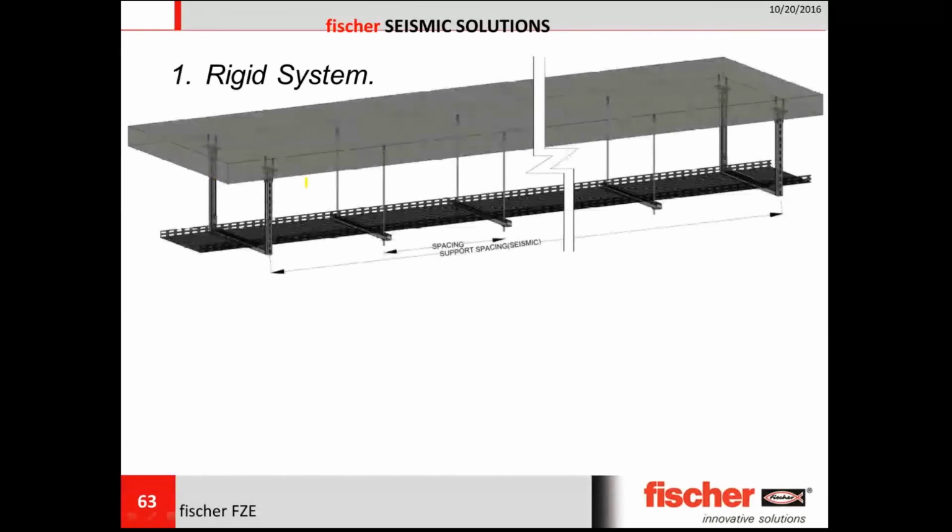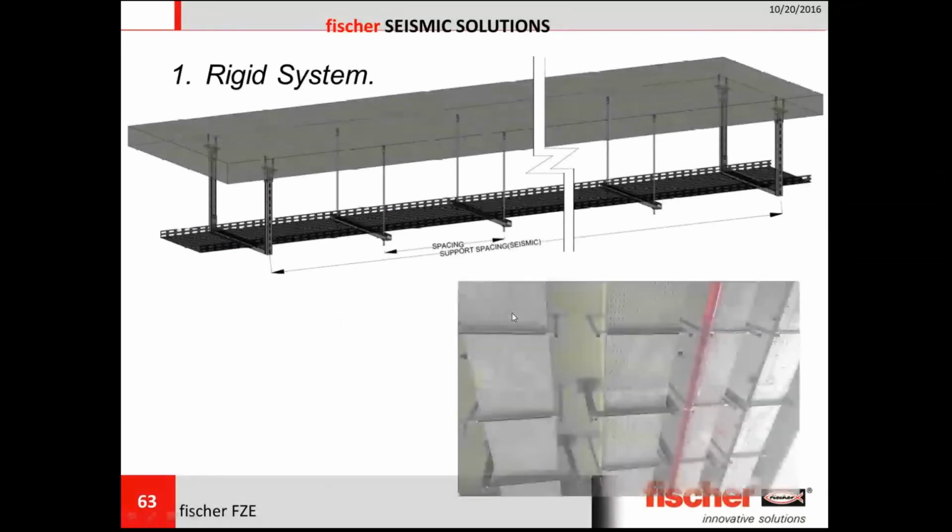As you can see, we are replacing at certain intervals normal threaded rod suspension with channel suspension, which makes the whole system rigid. It forms a frame, so in the event of an earthquake, it can withstand seismic forces.